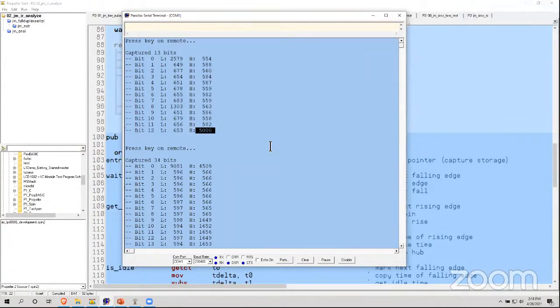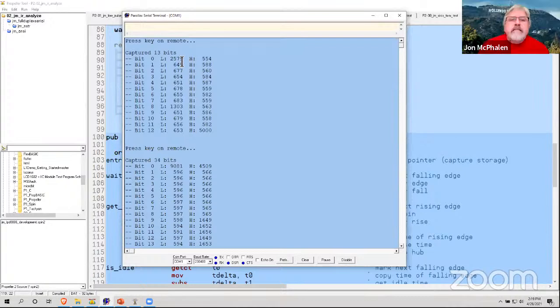So on that one, that's basically a 1 and 7 zeros and another 1 and 5 zeros. Yes, in this case, because here's the start pulse, and here's 1, 2, 3, 4, 5, 6, 7, so there's 7 zeros. That's command 0, because this is a Sony remote, this first one up here. And so that's command 0, which was the 1 button. And then there's a 1 and 4 more zeros. That's 1. Remember, these are LSB first. So this is the LSB. And the TV code is 1.